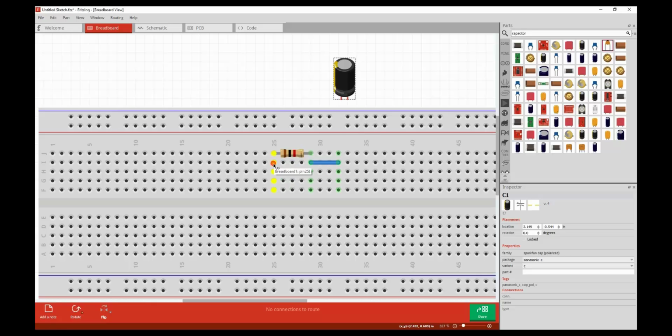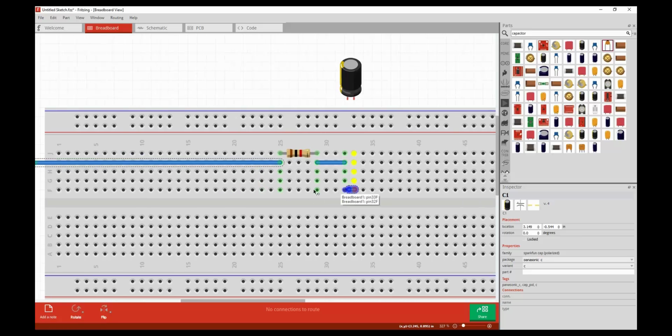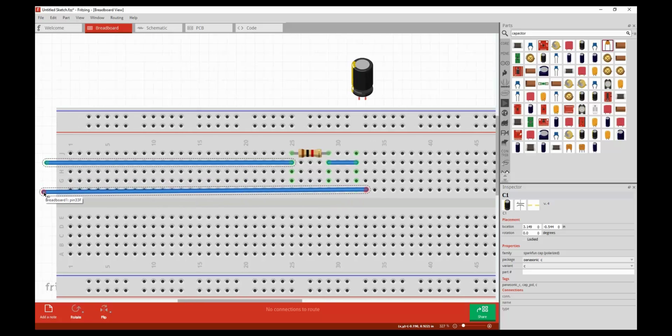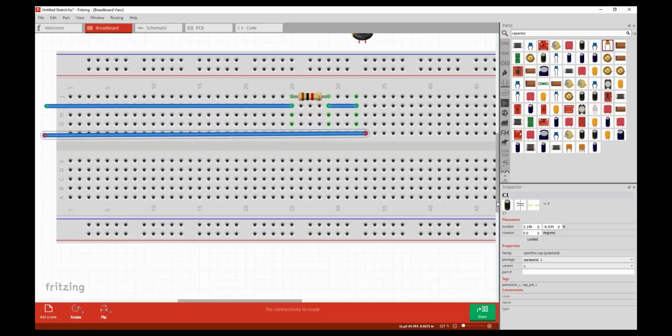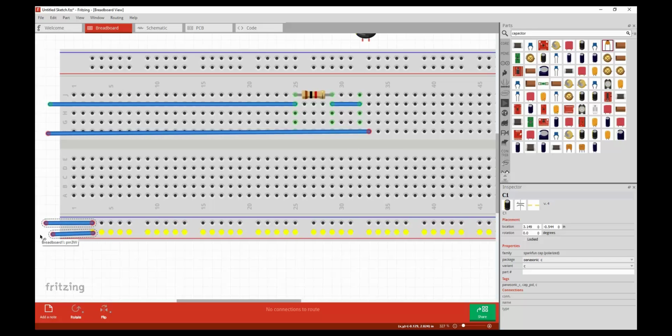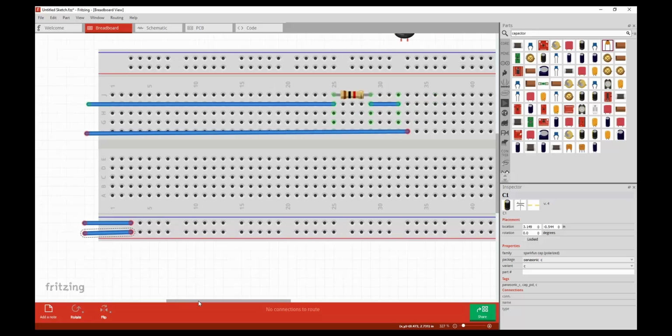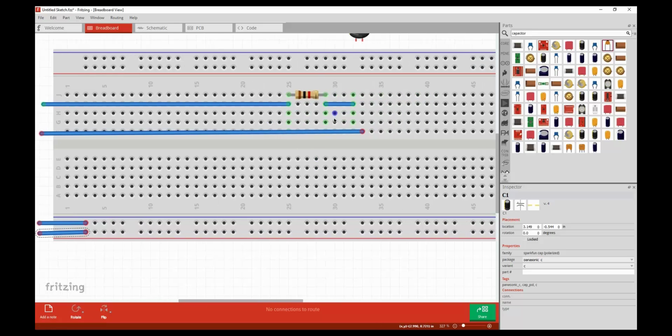I'm going to connect the plus side of the battery here and the minus sign of the battery here. You can also define these two bottom rails as positive and negative. You can just name them, keep them connected and keep them named like this. Say the top one is the positive rail and the bottom one is the negative rail. Just keep them like this, and any connections that you make on the breadboard, just make a connection to the respective rail. So you don't have to take this directly from here. So maybe I'll remove these.